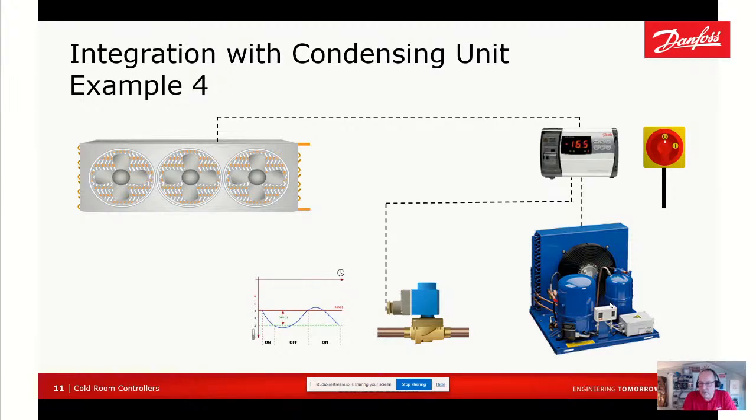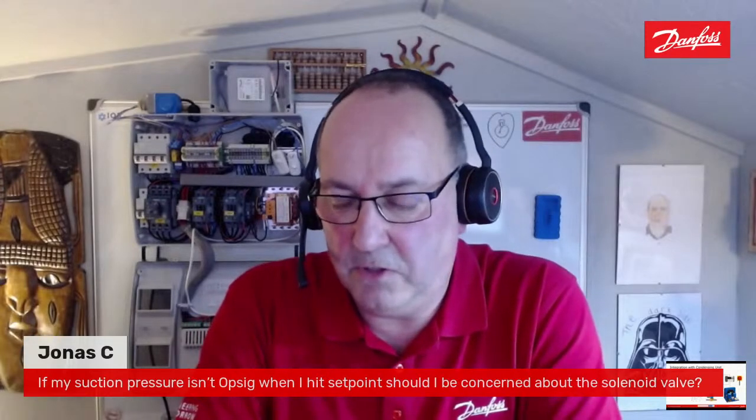A question's just come in from Jonas. If my suction pressure isn't at 0 PSIG when I hit set point, should I be concerned about the solenoid valve not fully closing? Well, it depends. It depends on the ambient condition. It depends on the refrigerant. In my time, again, many years ago, we always pumped down to balance point, and balance was always 0. If it does pump down eventually, then I wouldn't be too concerned.